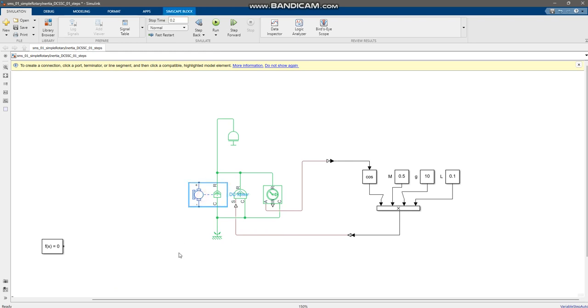So there are two terminals in this block, the positive and negative. We can either connect a constant voltage power supply, or we can connect it through motor controllers and PWM generators. We could add an H bridge over here and a PWM source prior to the H bridge and some signal to generate a PWM duty cycle, and connect these together and impart some sort of controlled voltage to the DC motor.